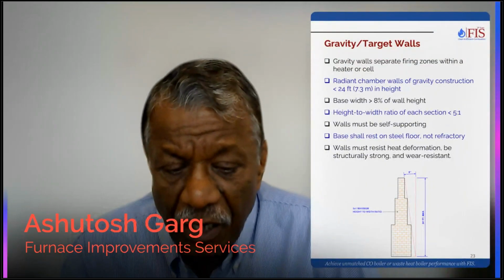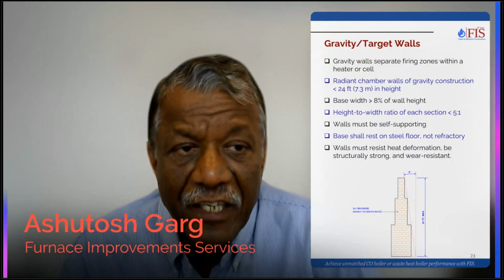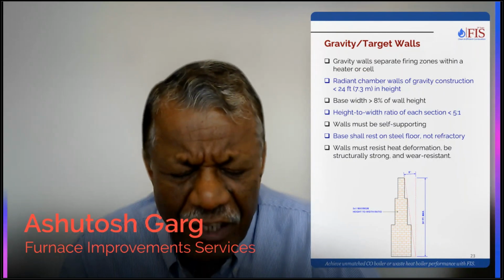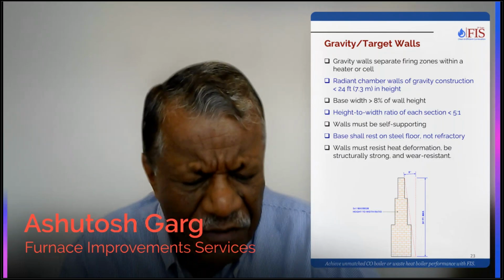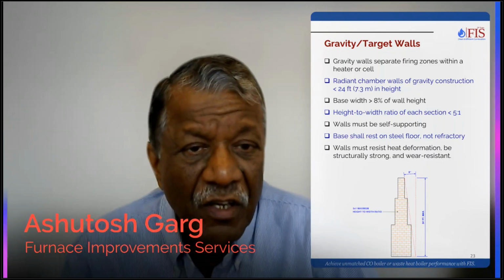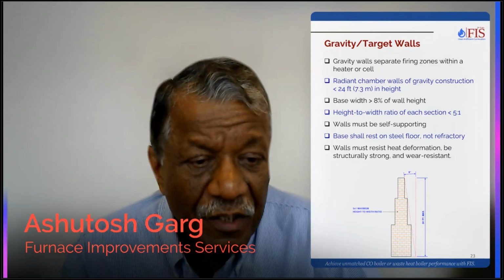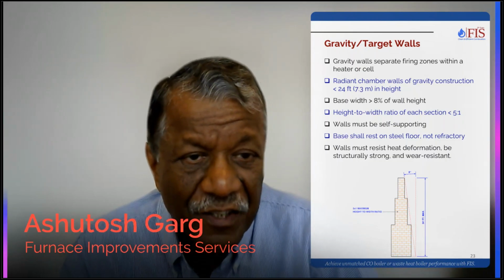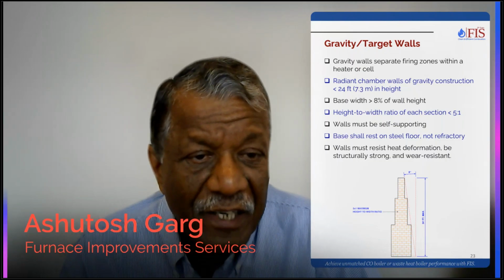So let's talk about the target walls. These are used in the heaters. No, they are not very common anymore, except maybe in some coker heaters, or maybe in some platformer heaters or UOP reformer heaters for dividing the cells. They are made out of high density firebrick,